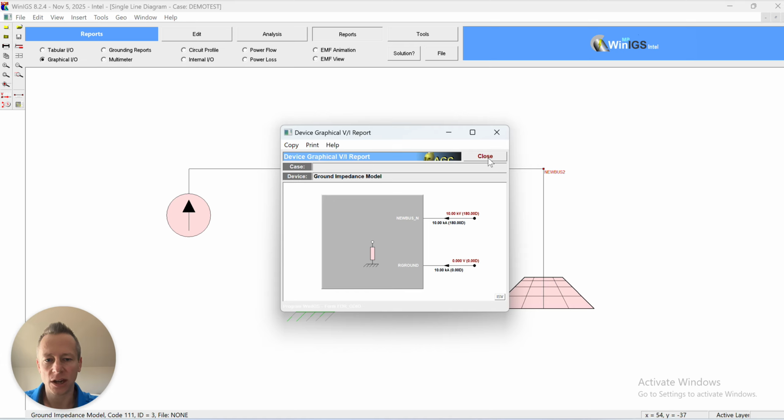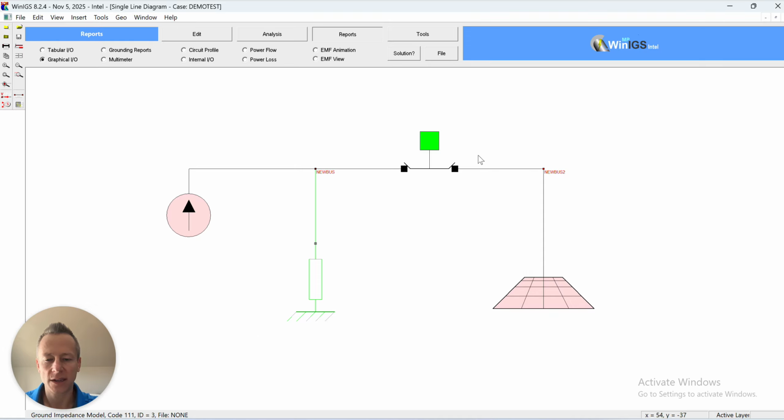That would be the GPR at the return back to the source, where all of that current gets sucked up through the 1 ohm resistance to earth. And again, this isn't a 1 ohm resistor. This is a 1 ohm equivalent resistance from remote earth to the point where it comes out of the earth. So think back to the dirt resistors that we had built in one of the previous videos.